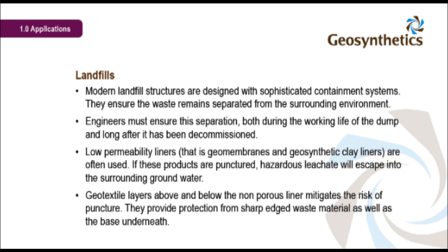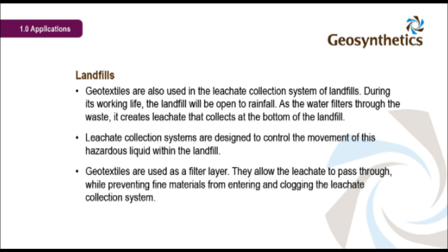Geotextile layers above and below the non-porous liner mitigate the risk of puncture. They provide protection from sharp-edged waste material as well as the base underneath. Geotextiles are also used in the leachate collection system of landfills. During its working life, the landfill will be open to rainfall. As the water filters through the waste, it creates leachate that collects at the bottom of the landfill.